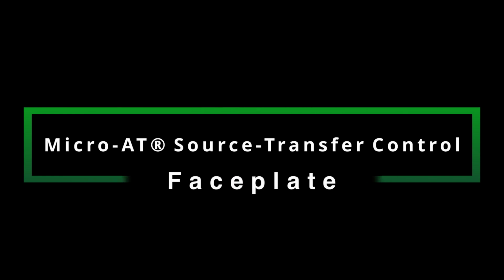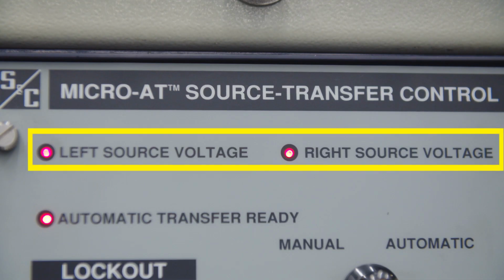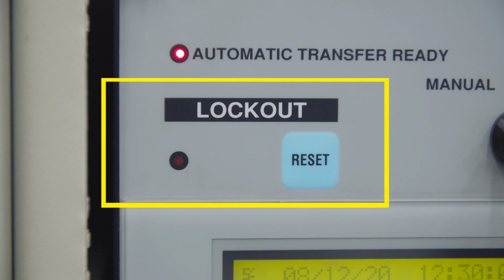Let's look at the faceplate of the control. The left source voltage and right source voltage lamps indicate whether each source has voltage. The operation selector switch is used to switch the control between automatic and manual mode. The overcurrent lockout indicating lamp will light when an overcurrent in excess of the predetermined lockout setting is detected.